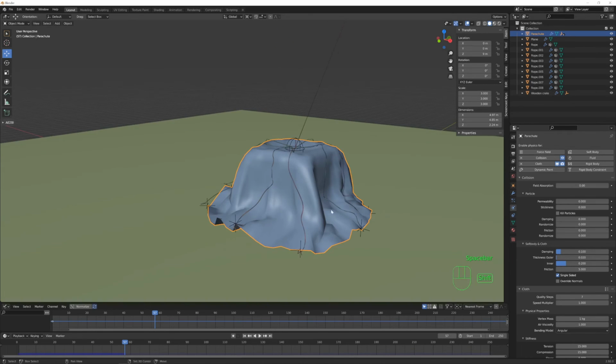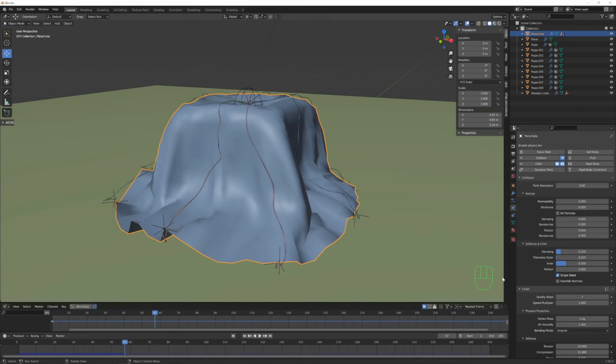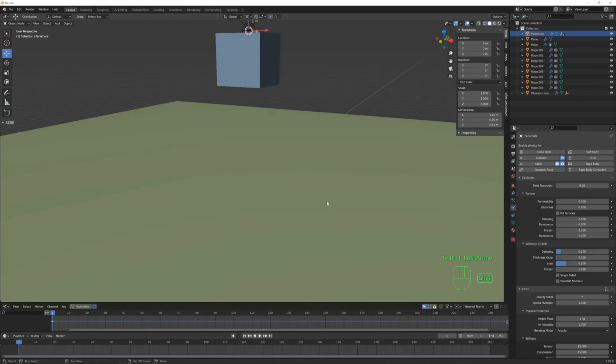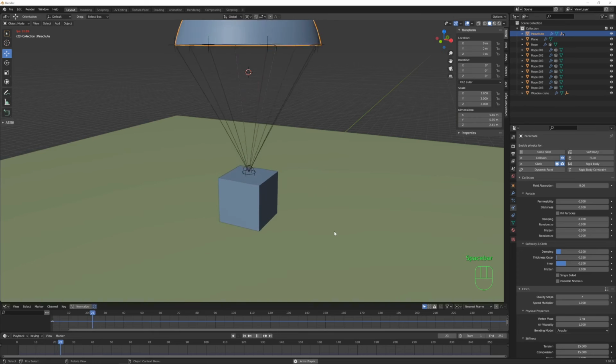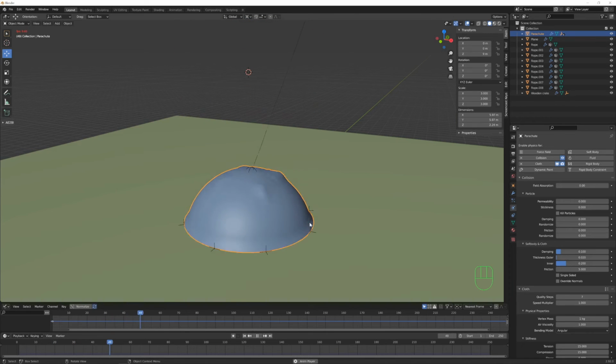And it seems that it's not working, and that's because under the collision in the soft body and cloth panel properties here, we have this single-sided option turned on, and because this has no thickness, I think we have to uncheck this option here. If I now try once again the simulation, yeah, and you can see that now the ropes are staying and colliding also with our parachute.